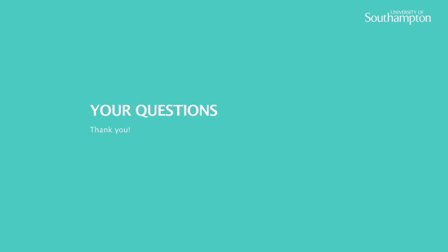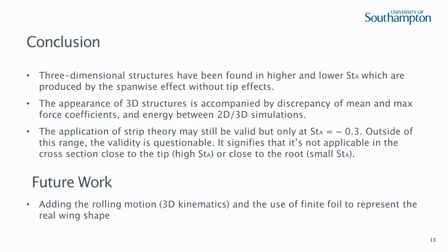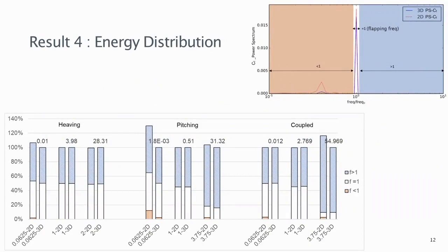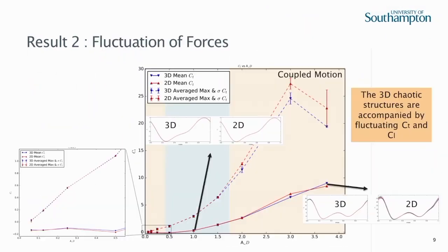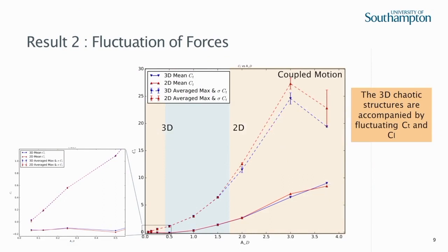So in the regime when you have the lock-in of the frequency, in the 2D regime, is the lift to drag ratio optimal or not? What happens to the lift to drag ratio? I'm sorry, I did not pay attention to lift, we just focus on drag because this is propulsive flapping. But the tendency between lift and drag, thrust, is the same.